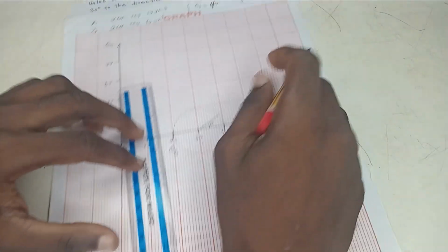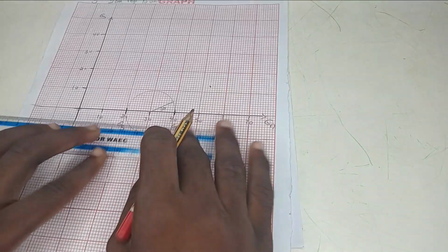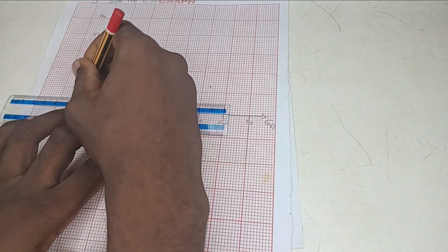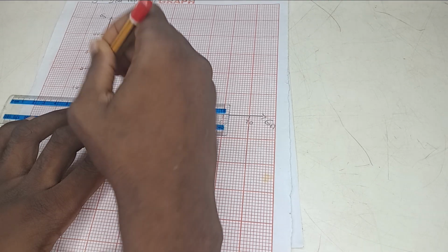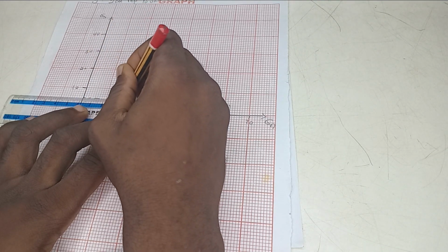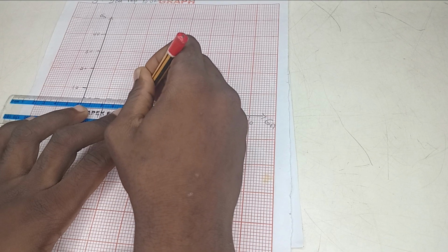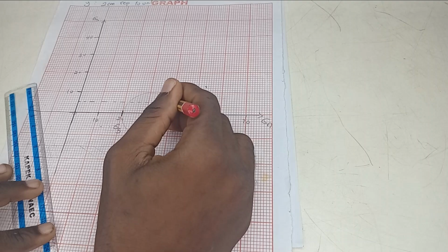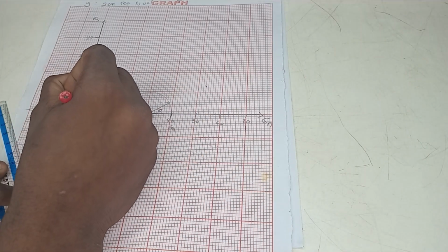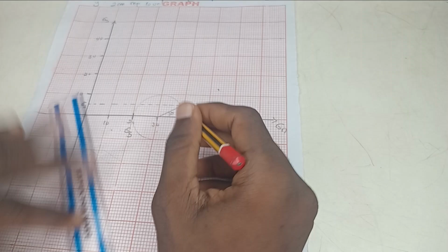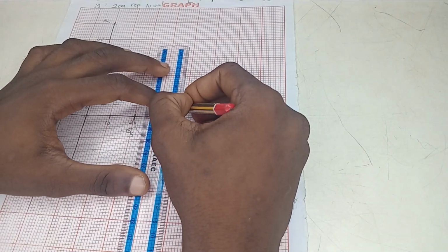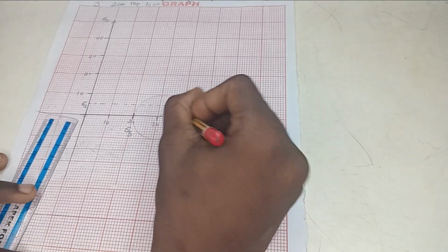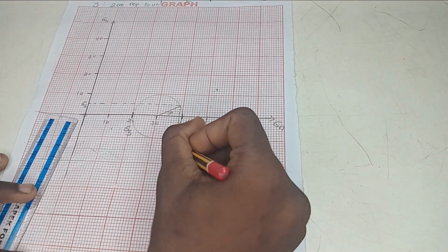Next, for you to get the shear stress and the normal stress, for the shear stress, you will draw a broken line from the y-axis to that point where the line touches the edge of the circle. Can you see? Any answer you get here is your sigma s. Then for you to get your sigma n, you do this. Any answer you get on the x-axis is your sigma n. Okay, good.